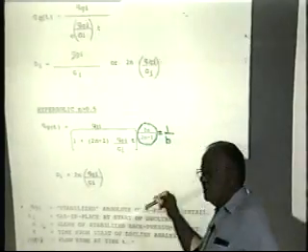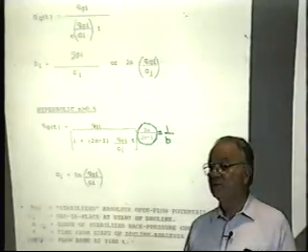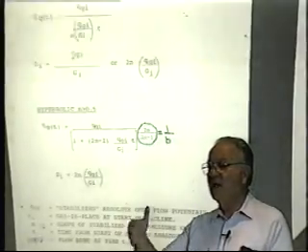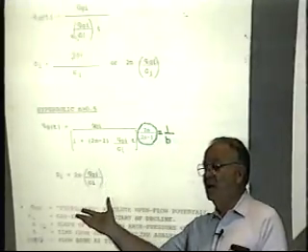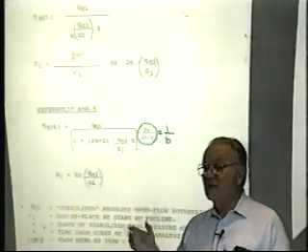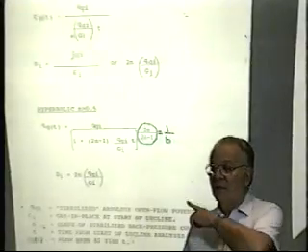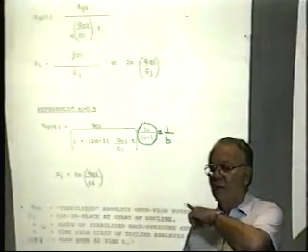Your QGI is a point on a stabilized back pressure curve. That's all it is. So if you have a KH and a skin from a build-up test, you just take the basic flow equation for pseudo-steady state. You calculate the back pressure. That's the Q sub I.